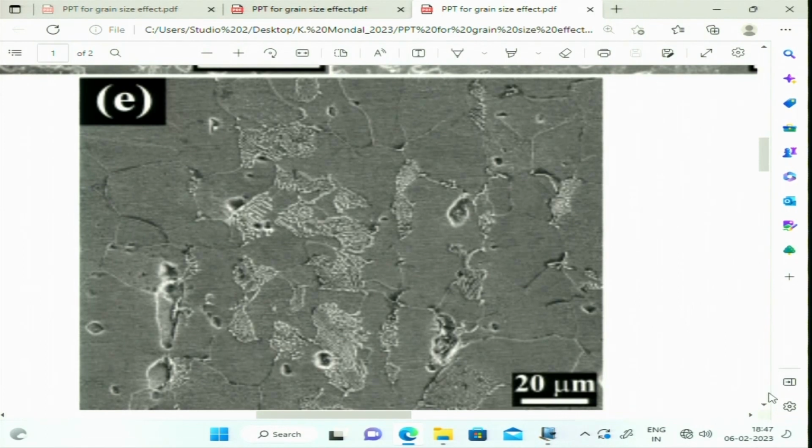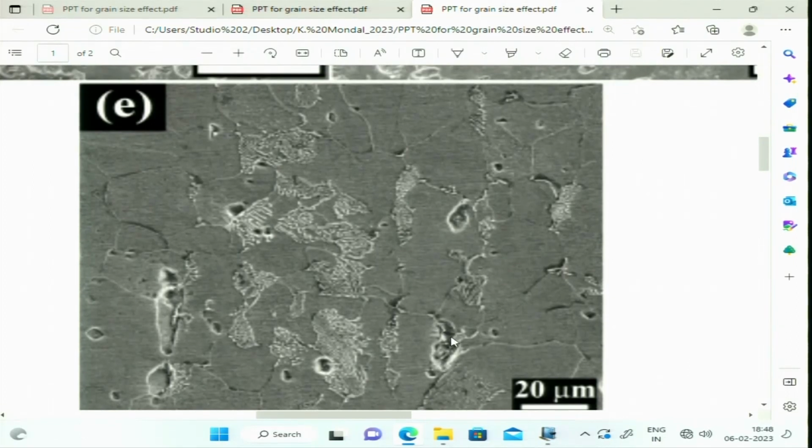And now we have also observed some interesting features. Here we also see pits. So, this is one pit, this is another pit, this is another small pit, this is another pit. Wherever my cursor is moving, you just follow that cursor, you will see those pits have actually coalesced, and then it is forming a kind of deep line along the grain boundaries, and everywhere you could see, for example, here if you see this part, here also it is showing those pit patterns are actually combined, and then it is forming a kind of a groove.